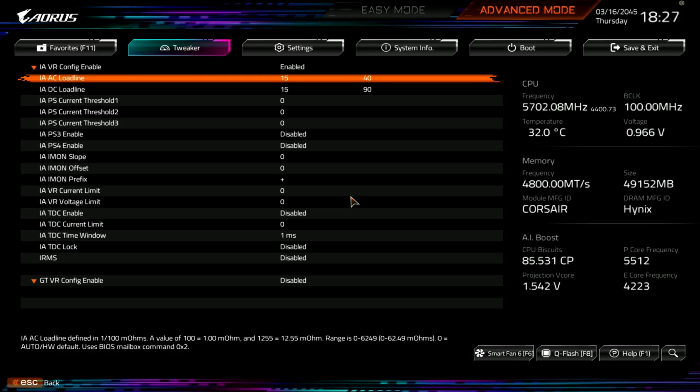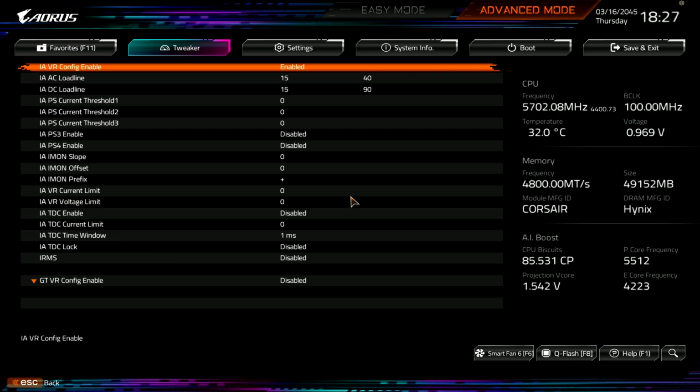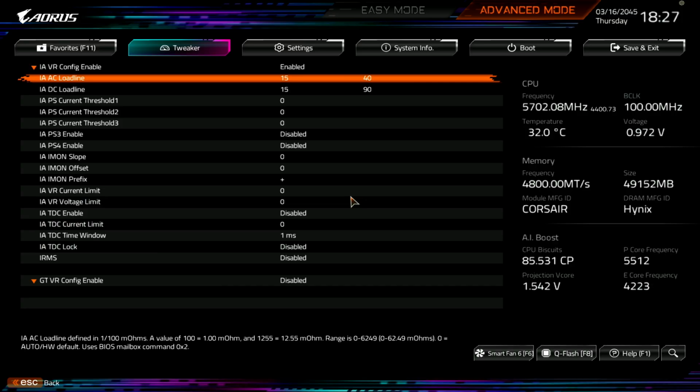Basically, if your AC load line is too low, it's going to trigger CEP. You can test for this yourself, because I'm not 100% certain that this is truly consistent across all motherboards. You can leave CEP turned on and just adjust the AC load line up. You could start with 1 and CEP is going to be very upset. Then you can go in increments of say 5 until CEP is happy and stops ruining your performance, in order to really dial in the AC load line.